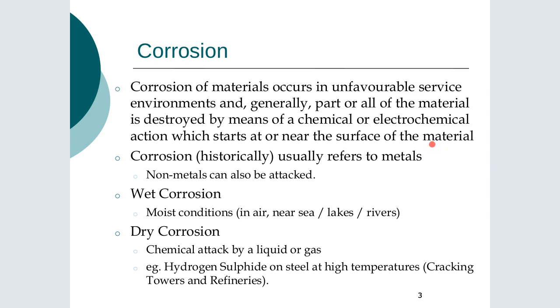What corrosion does is remove that material, strip it away, or not necessarily strip it away, but make it unavailable for the intended design use. If we link back to the reliability slides where we had the strength distributions, what corrosion does is weaken the strength of the material as a function of time.